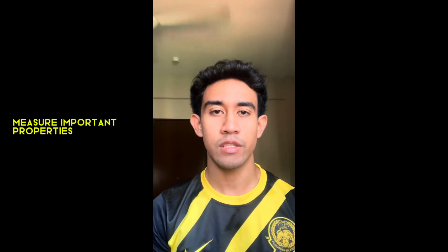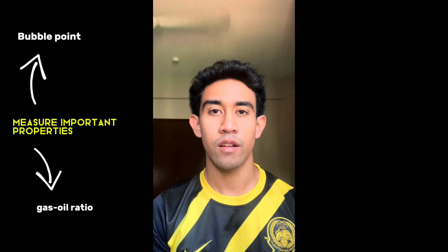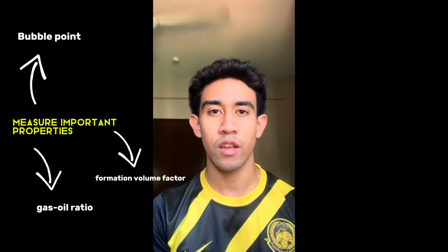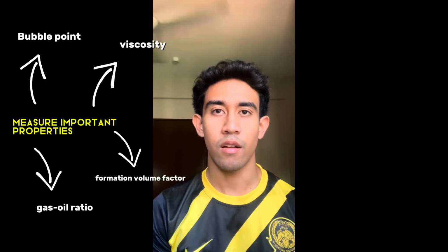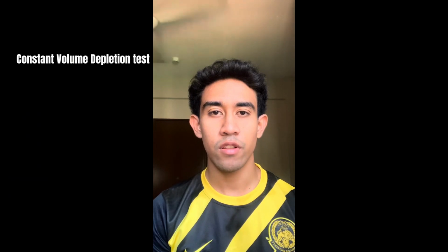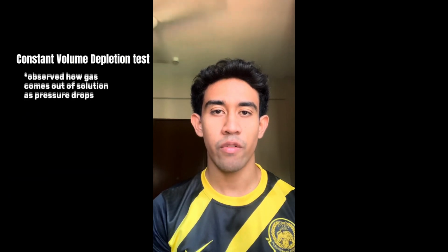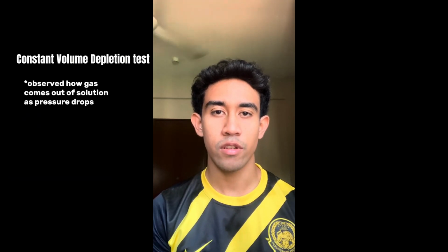These tests allow us to measure important properties like the bubble point, gas oil ratio, formation volume factor and also viscosity. For example, in the constant volume depletion test, we observe how gas comes out of solution as pressure drops, exactly like we learned when studying the bubble point in class. We also learn how the formation volume factor changes with the pressure, which is critical for converting reservoir volume to